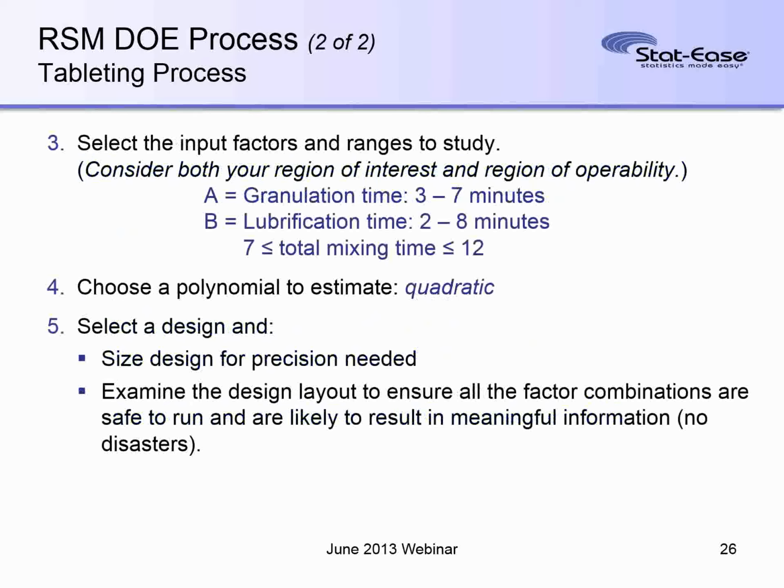Quadratic with a standard default design in Design-Expert is pretty safe. It gives you a chance to get a lack of fit test just in case it turns out that you really needed a cubic model. It also has the ability to project back to lower order models if you find out it was just a linear setup.